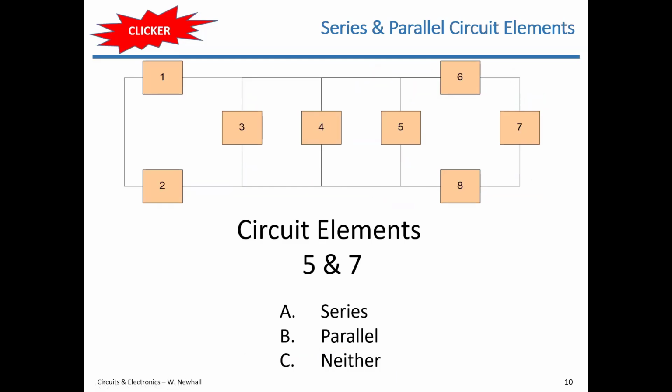Yeah, so if I could possibly annotate here, let's see if this works. If I draw, I think you're talking about right here, I put a circuit element, I call that 9, right? Would 3 and 4 be in parallel? No, they would not be. And the reason I say no is because if you look at the nodes to which 3 connects, you get this node up here, and the bottom node.